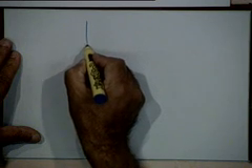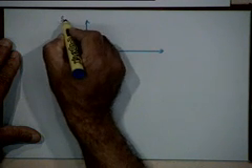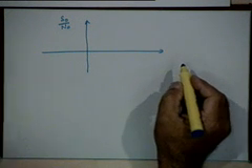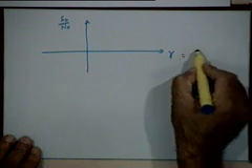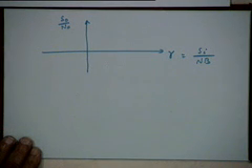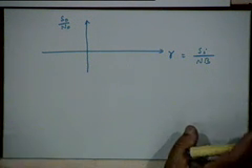Please remember that. Which means if I were to plot, for the case of the synchronous detector, a plot of the output SNR versus, let's say, gamma, where gamma, if you remember, is Si upon N B, the signal to noise ratio of the input in the message bandwidth.